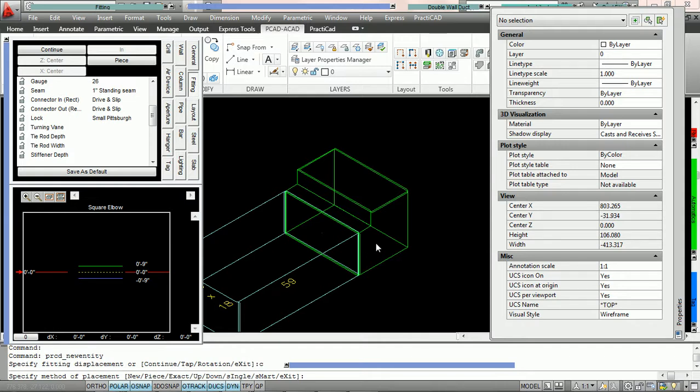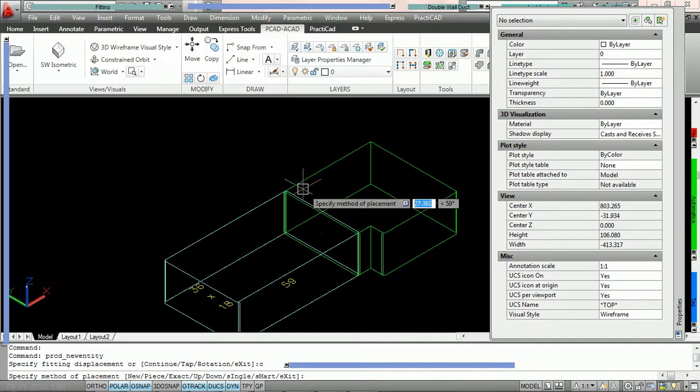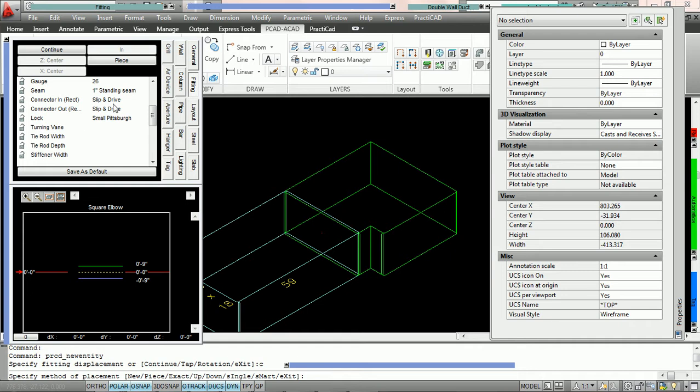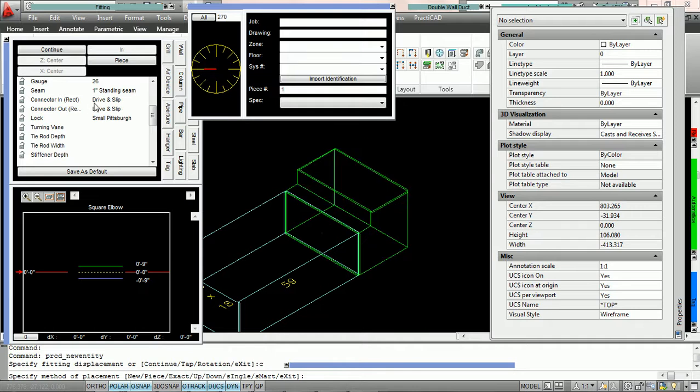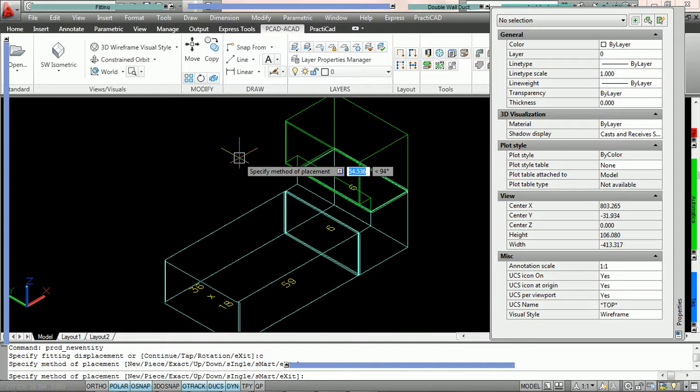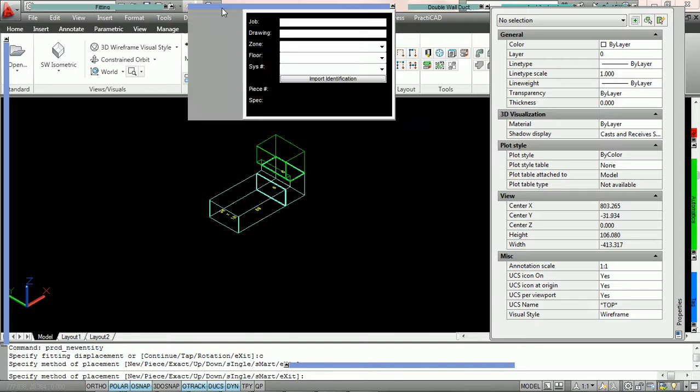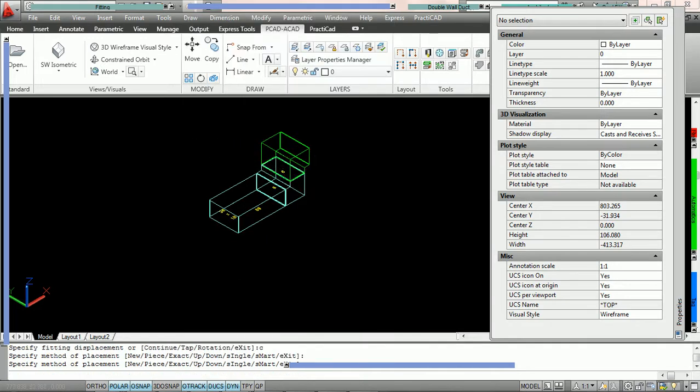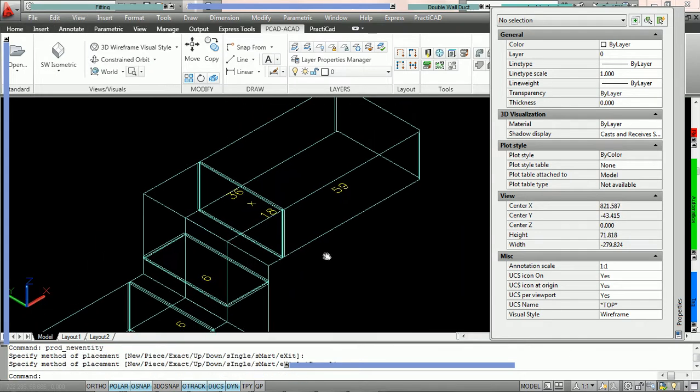So what we've got is the ability to just rotate our fittings using complementary connectors. And if we're going width to width, it uses compatible. If we're going width of one fitting to the depth of another fitting, it uses complementary. So here you can see we're going to attach an elbow. Then we're going to take this elbow, rotate it, and then add one more piece of duct.